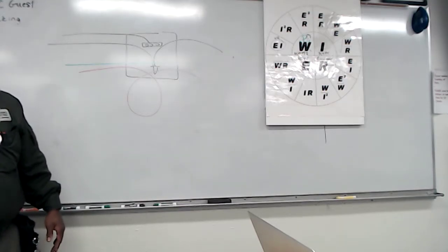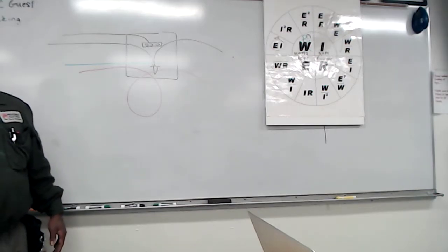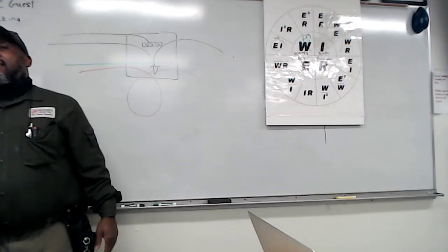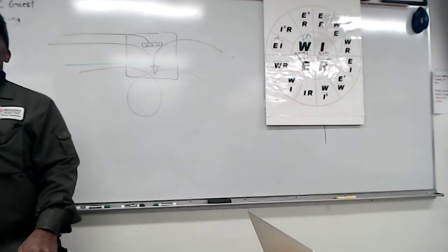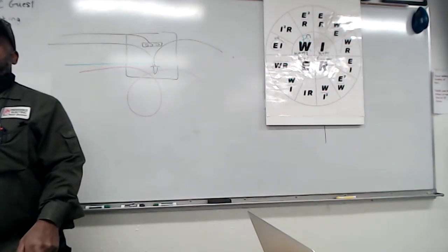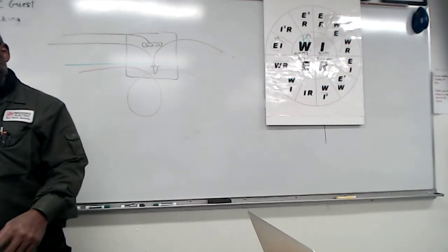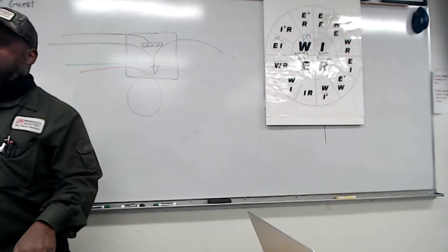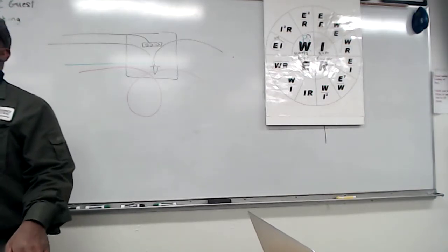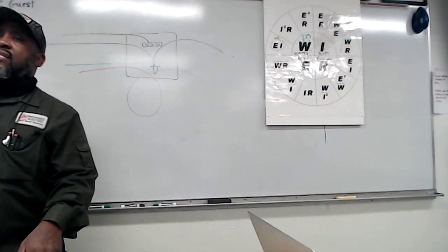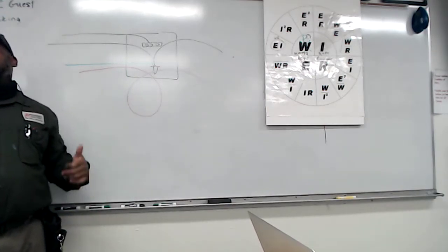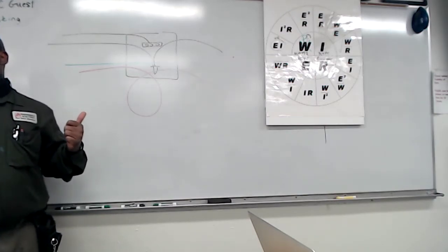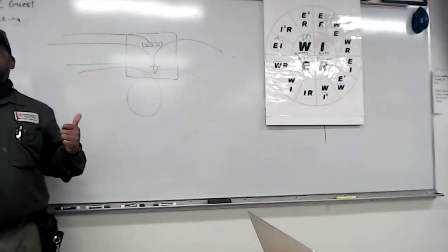Number 2 is clamps. I got that mixed up. Clamp fill: if I have an internal clamp, it doesn't matter if I have 4, 5, 6. If I have one internal clamp, it gets counted how many times? What does the code say? One time, one single allowance. And all of these are based on the largest conductor inside the box. So when I say one allowance here and 2 here, it's based on the largest conductor. If you have a 14, 12, and 10, what allowance are you going to be using? 10.